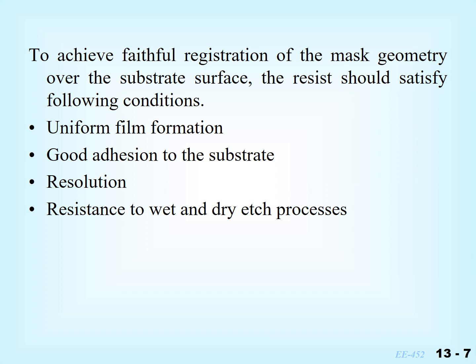It has good adhesion to the surface, that means a good sticking property, so that it is attached to the substrate or wafer. The radiation source must have a good resolution, and the photoresist should be such that when it is exposed to certain radiation, it changes its physical property. That means it should become stronger or weaker. Depending on that, we can design the process.